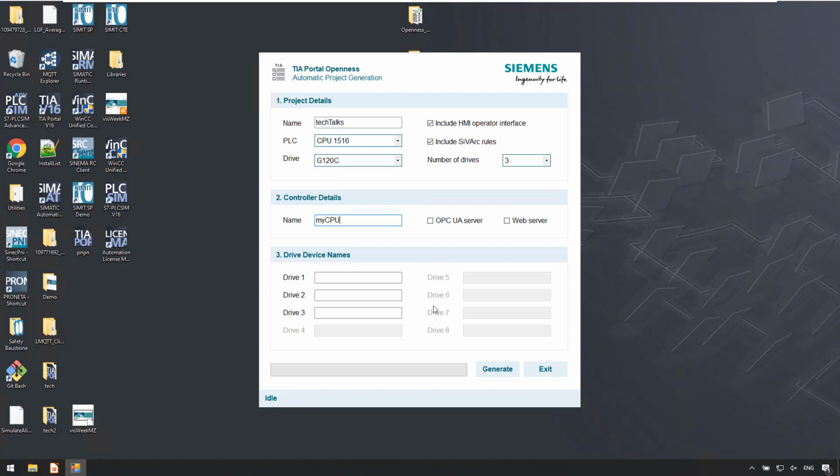Or even, let's adjust this story. Let's say that we as the OEM, we make packaging machines, and lots of our customers use PackML. So that's a companion specification for OPC UA. For this, then, we will need an OPC UA server on the PLC. So if the customer decides to pay for this functionality, there you go. We can put a tick box for OPC UA server.